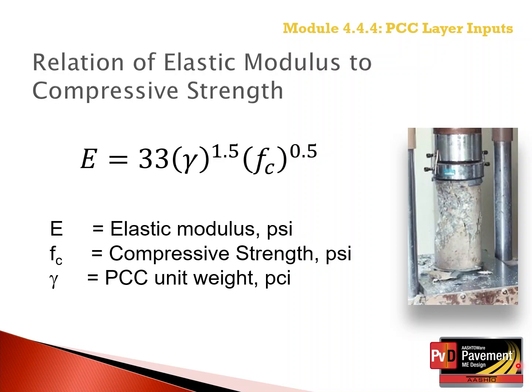This is the regression equation included in the PMED software for estimating the elastic modulus from the compressive strength and density of the PCC mixture. The regression equation is included in the Manual of Practice, section 10.3 of chapter 10.